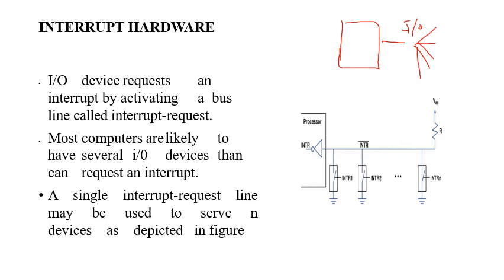This can be done by having external circuitry, or hardware, that is used to manage the resources. Here it is done using special gates known as open collector and open drain, which are used to drive the switch to ground, that is, open when the gate input is 0. So we have open drain or open source devices. In that case you have a gate. When the gate is 0, it is grounded, that is, this pin is grounded. When INTR is 0 it is grounded, and when it becomes 1, the internal switch turns on and is connected to the processor. In this way, n devices can be connected using a single pin.